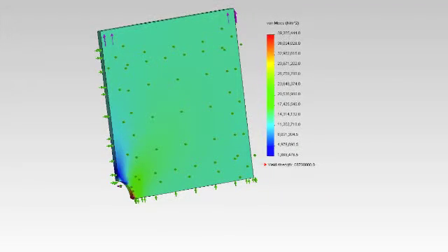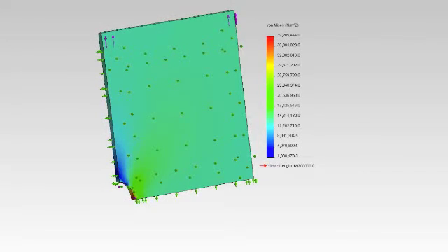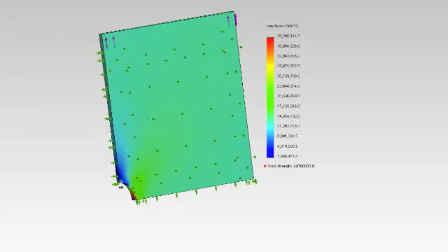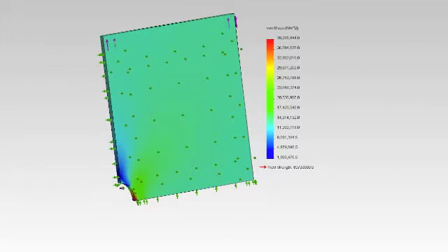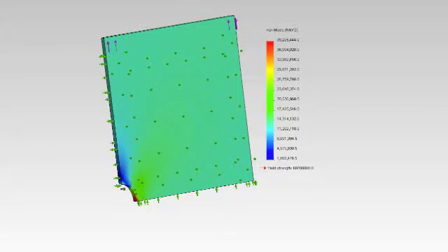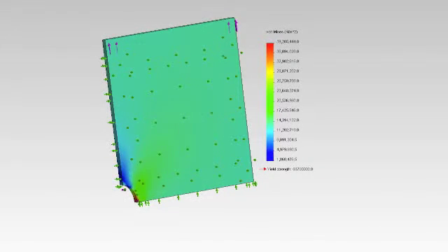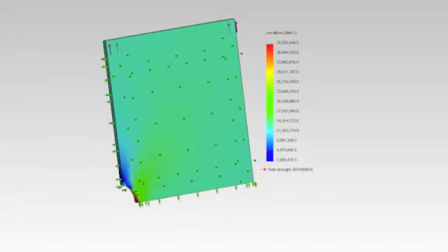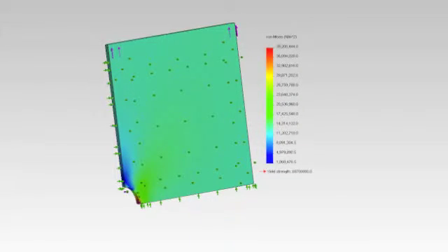With the use of our finite element analysis, we were able to obtain a plot of the vertical stress distribution across the plate. Our study showed that around the circumference of the hole, the stress distribution was non-uniform, whereas as you moved away from the center of the hole, the stress distribution became much more uniform. This is in keeping with Saint-Venant's principle, which states that when a point load is applied in the plane of a plate, the stress around the load point will be non-uniform, but by the time you move a width's length away from the point load, we can safely assume that the stress across the section is uniform.